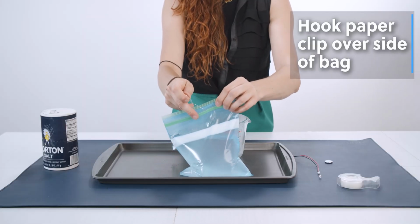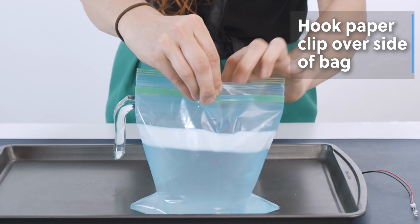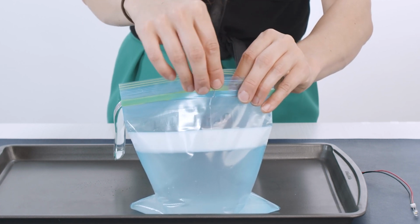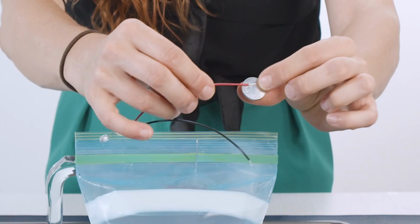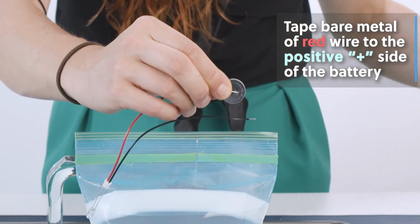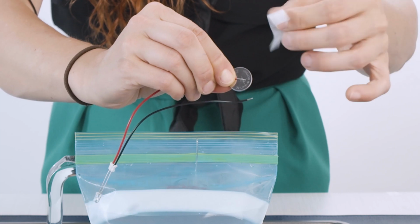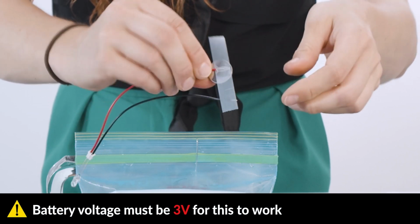Hook the loop over the side of the bag so that the straight end of the paperclip rests in the water. Tape the bare metal of the red wire to the positive side of the battery. The battery must be 3 volts in order for this to work.